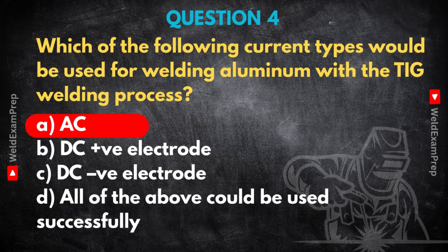As we just discussed, all heat on the workpiece for penetration, but zero cleaning action. Oxide stays put, leading to massive fusion defects, inclusions. Just bad news. This really does underline that theme we keep seeing. Understanding the material's basic properties is absolutely critical for picking the right parameters. For aluminum, AC isn't just better, it's the only way, really. It makes the process possible.